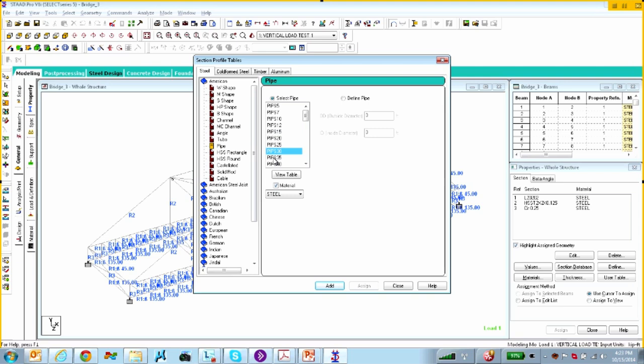like here, so you didn't use a standard pipe, you used a defined pipe. Yes, ma'am. Over on this side. Okay. And it does work in the code check. I just wasn't sure if I could really trust it down to a 0.98 ratio or whatever. I don't know how accurate it was or if it was kind of over-judging.